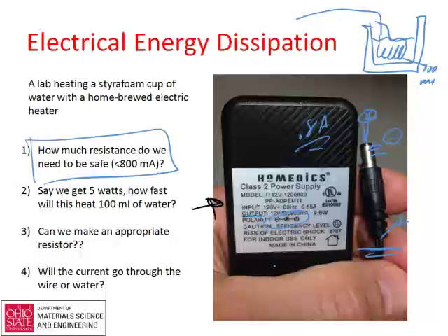You can answer that by just looking at conductivities, and you see that the conductivity of the wire is much, much higher than that of the water. So while a little current might bleed through the water, most of it's going to go through the wire. And what you can also do then is measure the current that goes through this thing, the ammeter, and then separately measure the voltage across here.